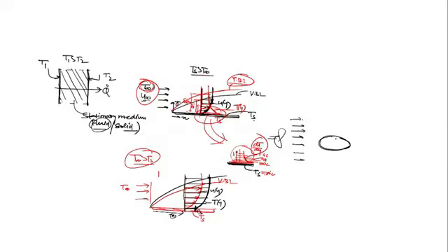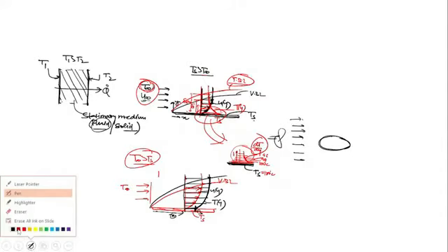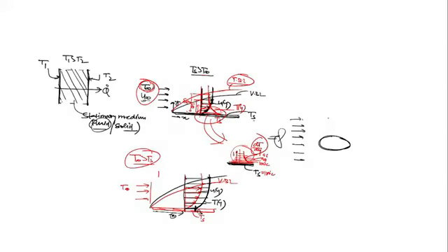So how will the boundary layer develop, how will the thermal boundary layer and velocity and temperature all develop here? Whenever any fluid comes to the surface of the egg, that velocity becomes 0, and as the fluid moves away from the surface, the velocity increases. This is the velocity boundary layer. Yes or no? Because any fluid layer which comes to the surface of the solid will have 0 velocity, and as we move upward in the y direction away from the surface, the velocity increases, and this is what we call the velocity boundary layer.